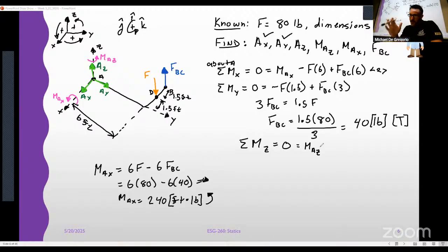These forces run completely parallel to the z-axis. They are not perpendicular to the z-axis in any way. And so the perpendicular distance between the z-axis and these forces is 0, right? So this moment is 0 for this loading condition. It's not always 0. If I had applied a force at some angle, right, instead of straight down, then we need to deal with that. But then you're also going to have an x component or a y component of that force too, right?